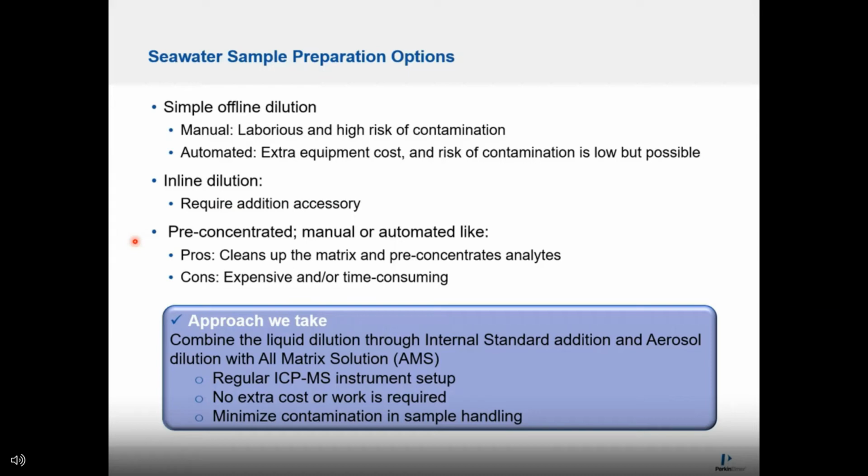The advantage of this approach is obvious. However, it adds additional costs to instrument investment. It is not an easy approach as you need to really take care of the columns, prepare the buffer that must be metal-free, and it lengthens the sample-to-sample analysis time with loading, pre-concentrating, and backwashing steps.